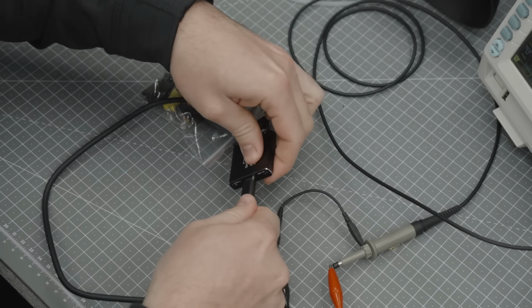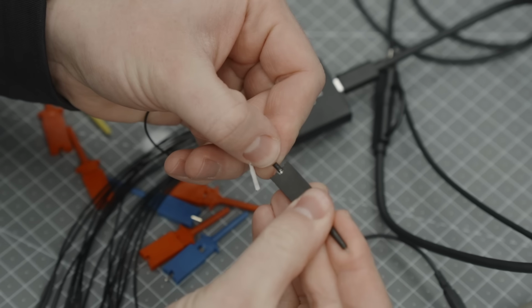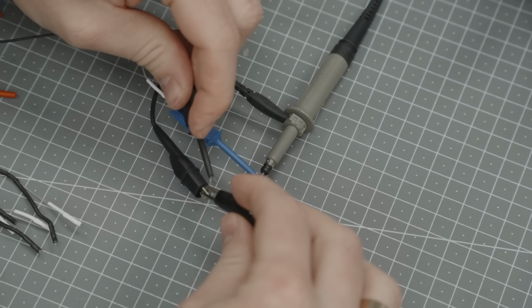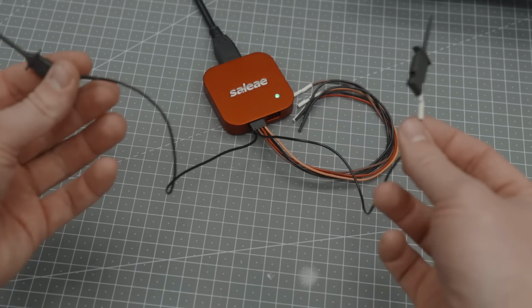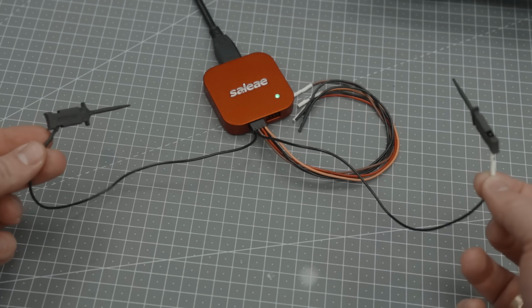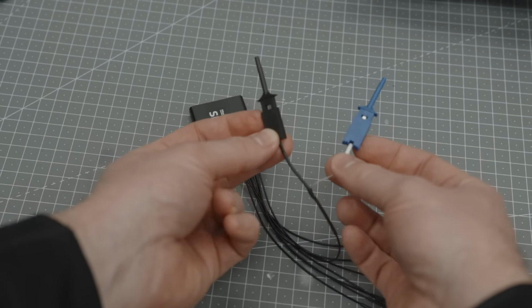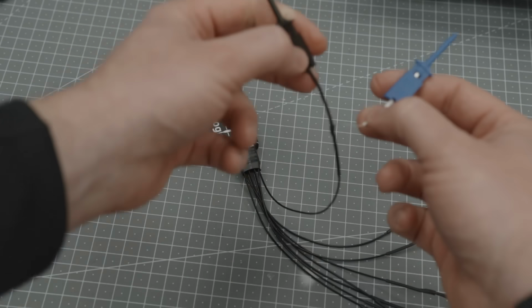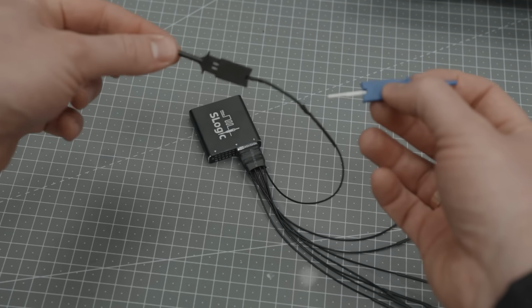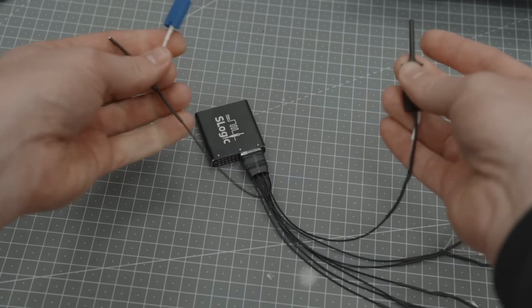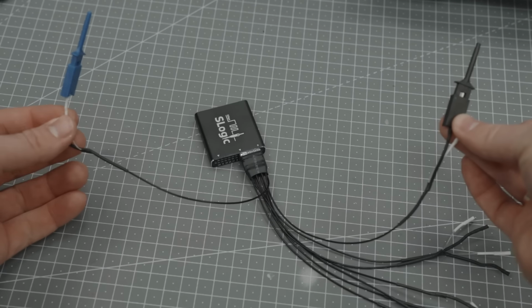As the name suggests, it has 16 channels, which is nice, but actually I rarely ever need more than 4 channels simultaneously. The Aliexpress has individual leads for all the channels and ground connections. Here we have a single coax per channel that exposes the signal and ground connections at the end. While this is probably better for signal integrity, it can be tricky to connect your subject as the leads at the end are short, but I could always use the ground from a different channel if this ever gets in my way.